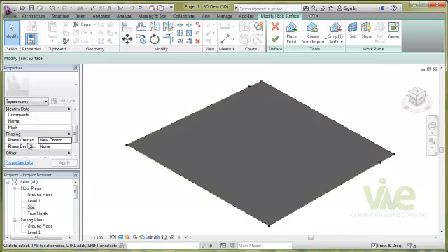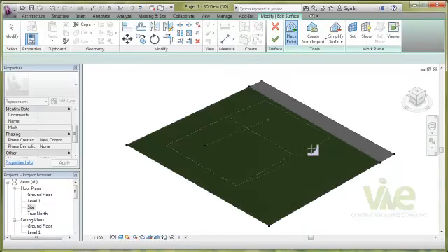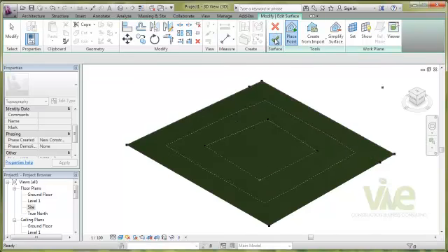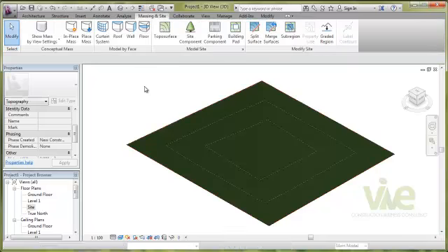Okay, there's our topo surface that we created, and you can see that it's now under new construction. So any changes that I do to this topo surface, which is a topo surface over the existing one, will reflect a net cut net fill value to my topo surface. So let's place some points at the center. I'm just going to take my place point tool and establish a 2000 millimeter elevation. A couple of points at the center. Okay, I'm going to go ahead and click finish.